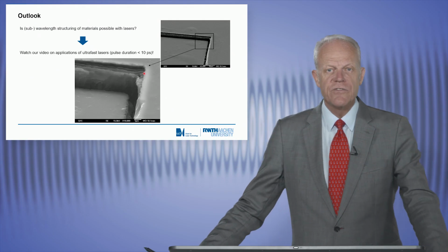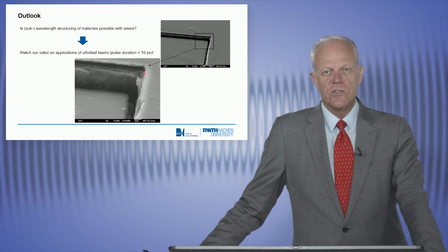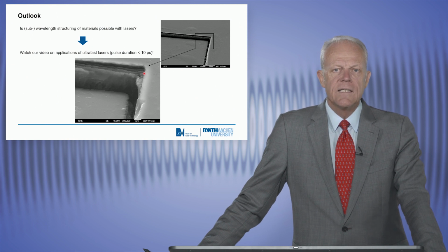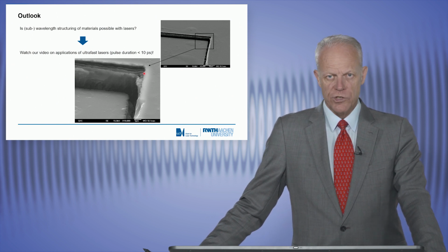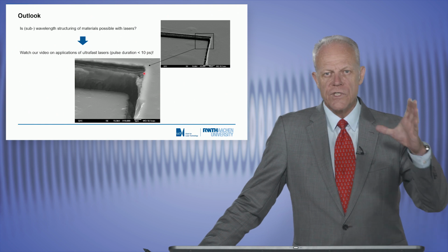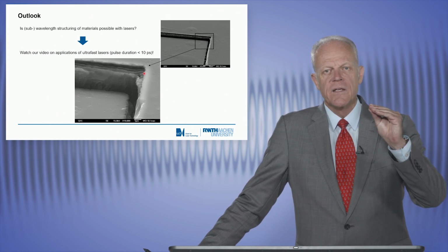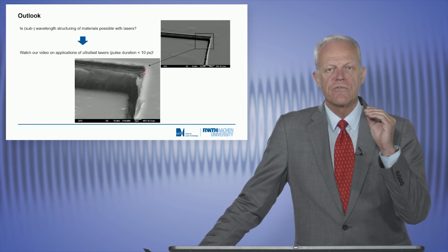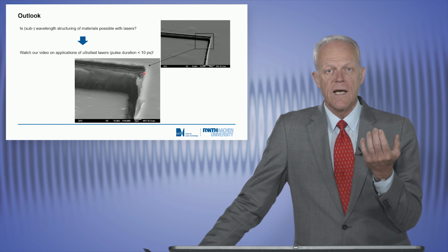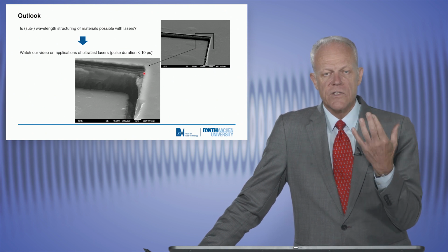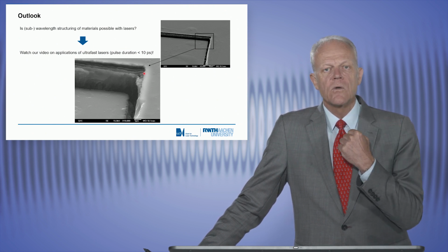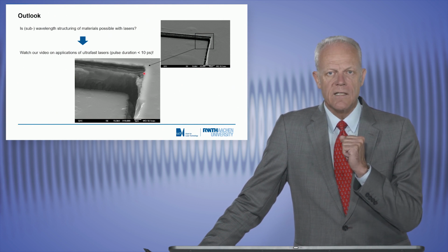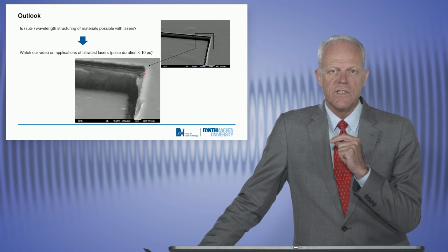So this summarizes the video on laser drilling, and you have seen the 4 different processes that are applied today. As a natural evolution of the consequence of reduced melt film thickness with shorter pulse lengths, people developed picosecond lasers, femtosecond lasers of real high powers up to several hundreds of watts, kilowatts, in order to scale this wonderful ultra-precision process, which we will handle and take care of in a separate video.